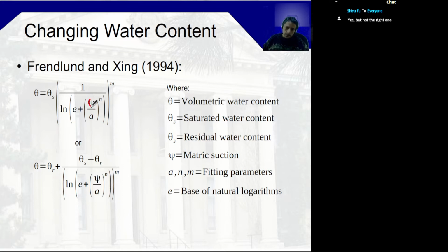So this suction value there is the negative of the pore water pressure when we are assuming that atmospheric pressure equals 0. And so between each step, you basically have to recalculate the hydraulic head, because hydraulic head is equal to elevation head plus pressure head, right? So from water content, you calculate pressure, and so they become fairly complicated to handle.